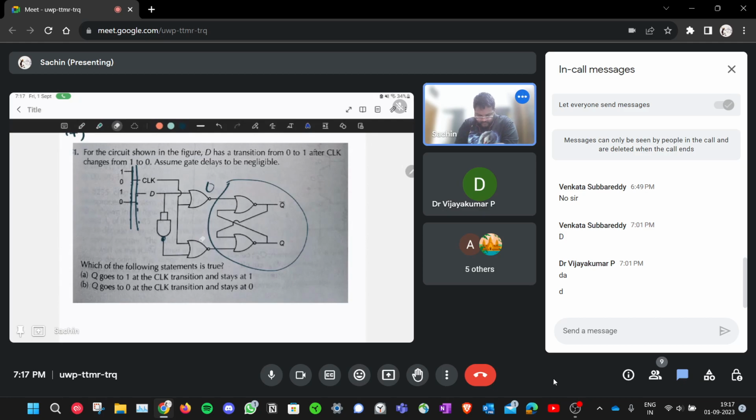So that's the previous state. And then when both clock and D are low, this will go to 1, and this will go to 0. This will stay at 0 because D bar is 1. So this will stay at 0. Now you have 1 0 to the SR latch.